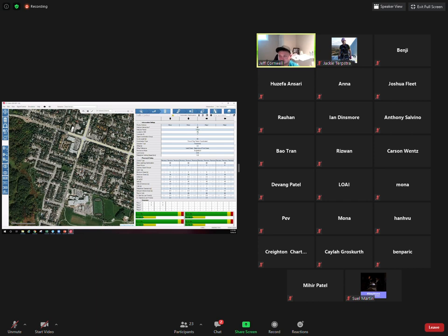So now they're both 90. This button here just optimizes the splits. They were already optimized, so nothing is changing. And it makes sense because I did this intersection fixed time with an exact equal amount of traffic on Stonechurch and the exact same amount of traffic at Upper Paradise. It's giving me, of course, a 45 and 45 second split. So it's making it completely even. So that's what I would expect, which is why I did them all the same volume.